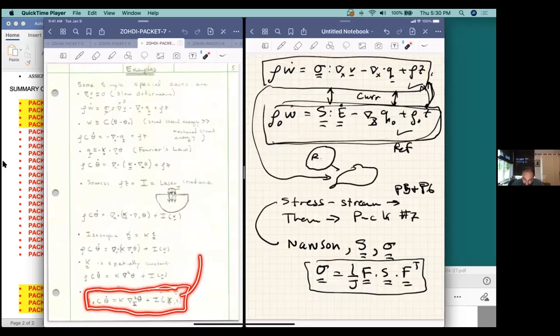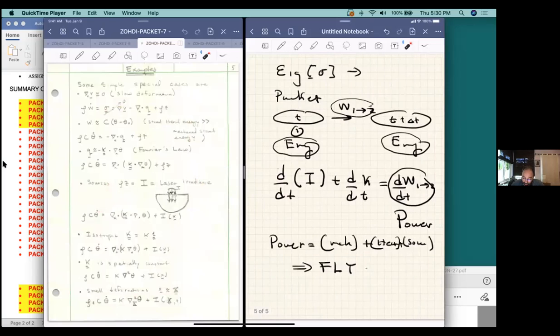So you can go from the heat conduction problem, there is a linear line all the way down from the first law of thermodynamics until you make certain approximations that you can get an equation that's relatively easy to solve numerically that happens to do, of course, with lasers. And oftentimes in laser analyses, we don't care about the stress power and the deformations are relatively small. Therefore, we only have storage of energy terms that are only thermally based. We don't have mechanical energy storage. So the problem, of course, becomes somewhat easier.